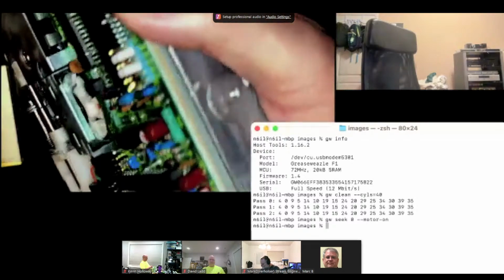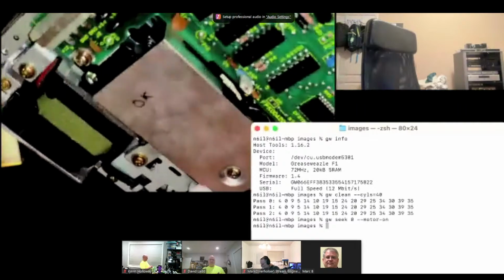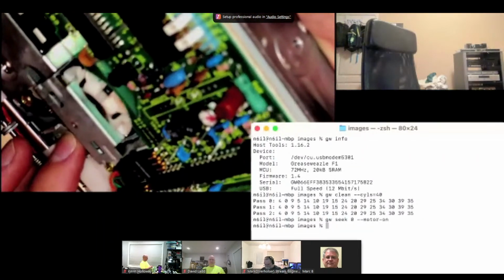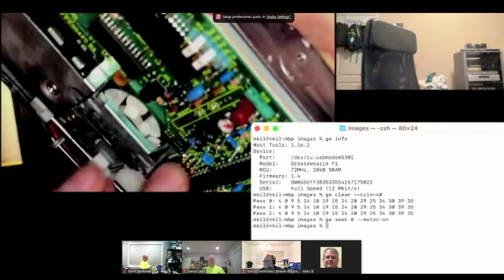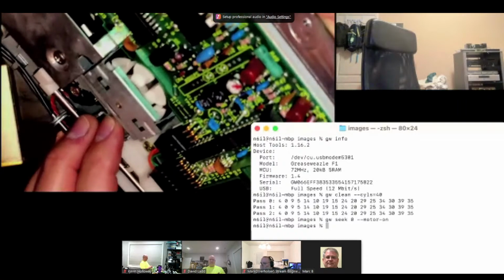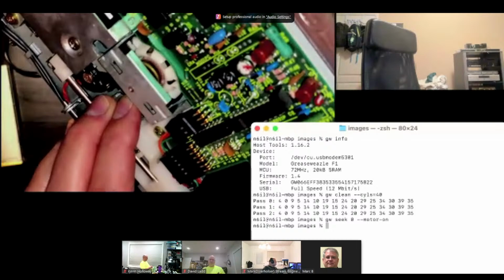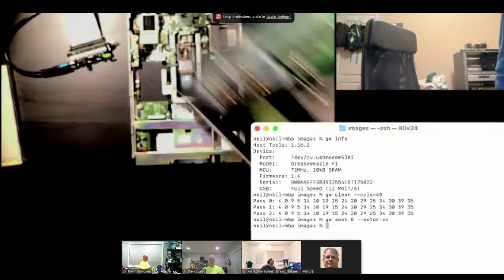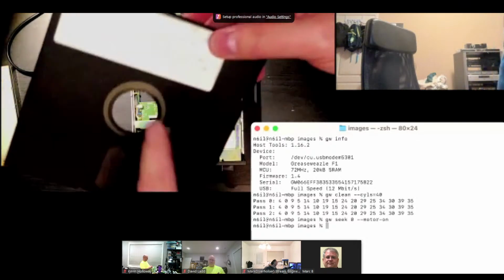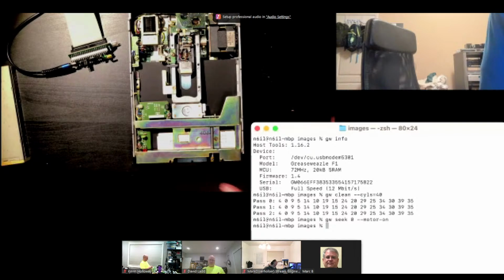So when you close the lever, you can see this hub moves up. It's not going to go down, but I can push it down manually. When you put the disk in, this hub here, this white thing, goes into the top of the disk, and it clamps down on the bottom part. So you want to close the door gently, because you want to make sure that this locks in on the center of the disk. Right, we're talking about the hub going into the center of the disk. So you don't just jam the lever down on this kind of drive.